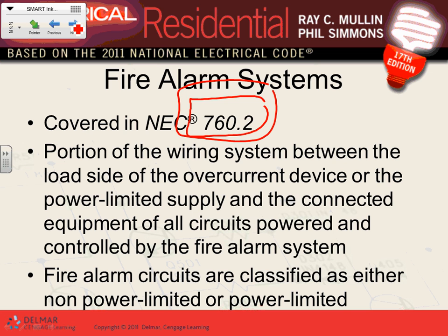Here you go. Power, non-power. These are the two types: non-power and power limited. Can you guys make a couple of checks here? Next quarter and the quarter after, next semester and the semester after, we're going to be always working with power limited fire alarm system, a 24 volt AC fire alarm system on the wall, and we're powering all these horns and strobes, and everything else is going to be 24 volt power limited. Can I have a thumbs up that we understand it?